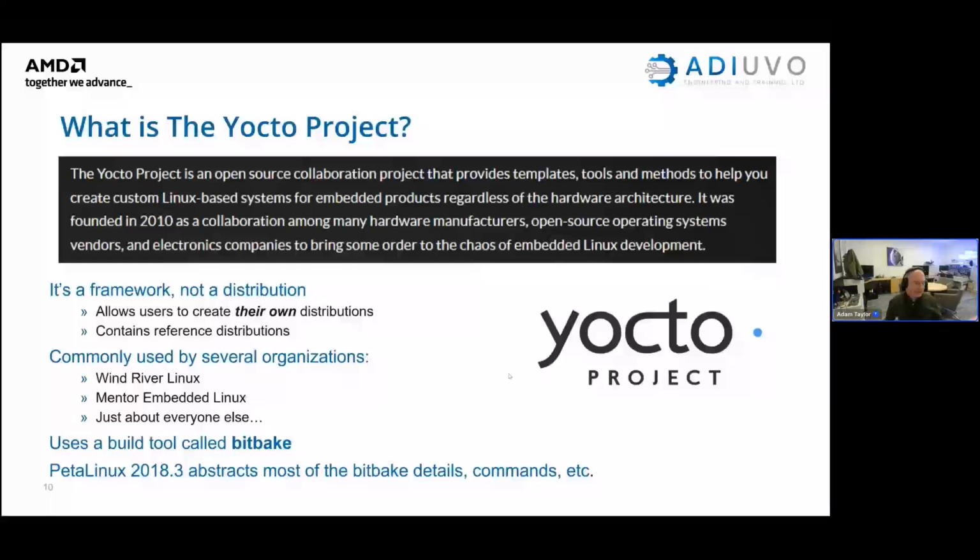So when you change from one target to the next, you don't really have to go away and learn how to get everything building. The build tool is called BitBake, and the elements that we create in there are called recipes. Those recipes will tell us how to create applications, or how to add in new layers and new drivers and such like.